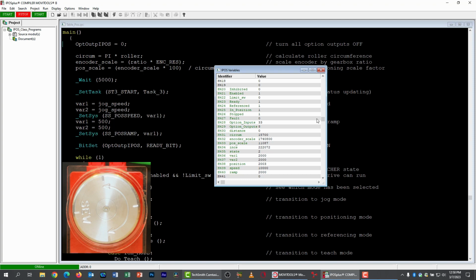I've turned my go bit off, and I'm going to pick row 2 in the table by turning DI15 off and DI16 on. I'm going to trigger my go bit, and I'm going to hit controller inhibit almost right away. So let's do that. Okay, as you can see, it started positioning. Now it's stopped. I'm going to turn DI12 off. And I'm going to turn controller inhibit back on. And we have gone back into the positioning state just like we should.